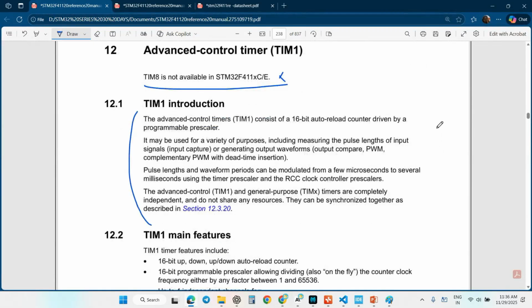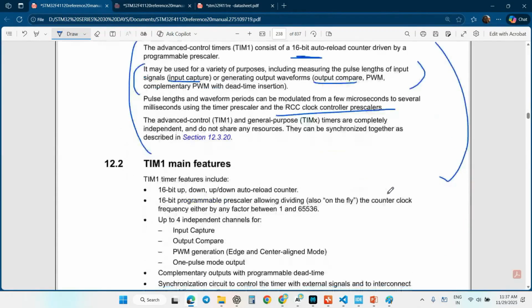The interaction part I already told you: they have given what bit of timer, what bit of ADC, and what registers and modes there are. In GPIO we saw input mode, output mode, analog mode, alternate mode. Likewise, to do PWM, they have given input capture mode and output compare PWM and so on. Yes, it is clock control.